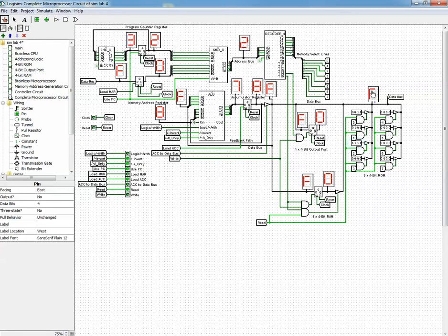Remember that this is an F and it is held on the data bus, and the memory address register has an input of a data bus. Right now it has been moved to the input of this memory address register. So how do I move it to the output? I need to enable this register by enabling the load MAR. So I'll set load MAR equals 1.